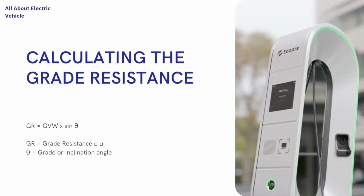Now, let us understand calculating the grade resistance. Grade resistance is the opposing force that a vehicle has to overcome when it is moving uphill or downhill. This force is caused by the gravitational pull of the earth and can be calculated by using the formula GR = GVW × sin θ, where GR is the grade resistance, GVW is the gross vehicle weight, and θ is the angle of inclination of the road surface.